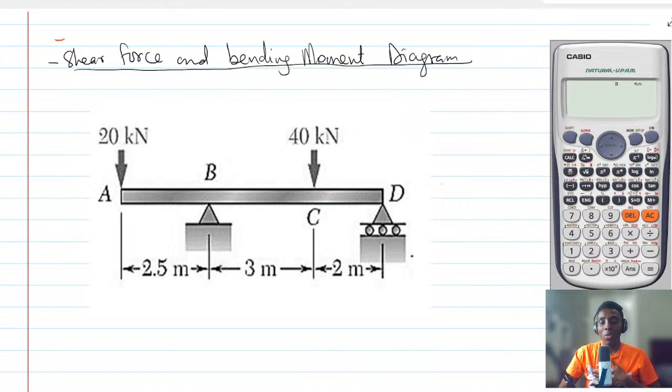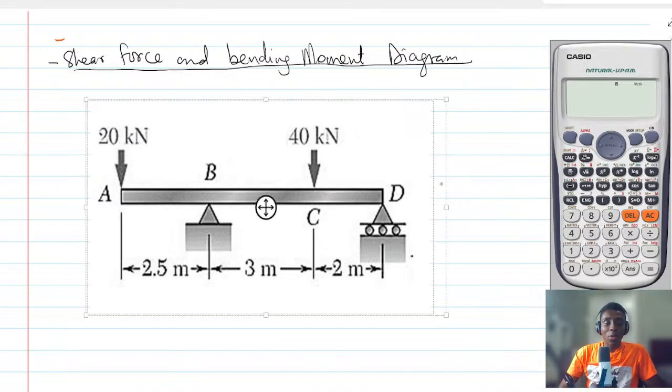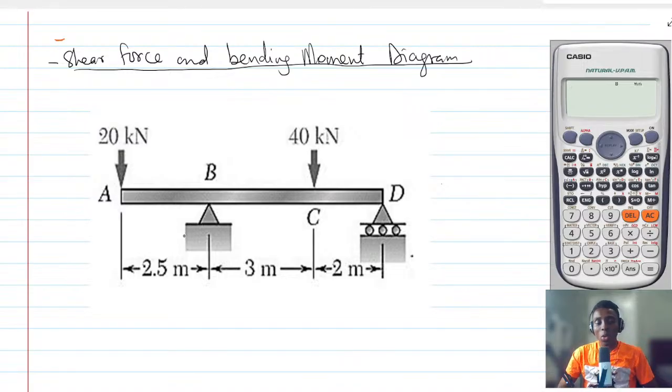First of all, you are going to start from your statics and solve for the reactions. I'm not going to waste time on that because I know that you understand equilibrium of rigid bodies. So I will go straight forward. First of all, find the reactions at the support. Here we have a pin joint, which is also called a hinge joint.